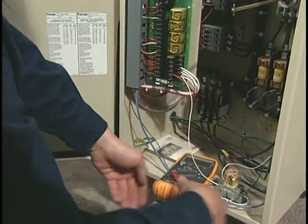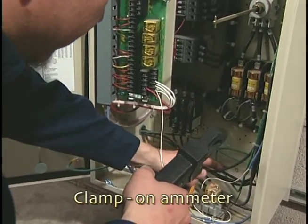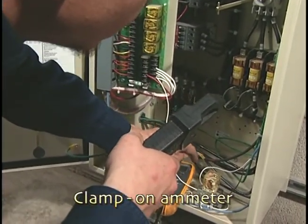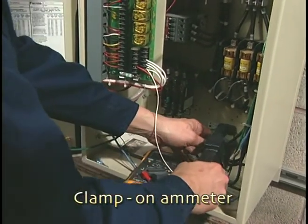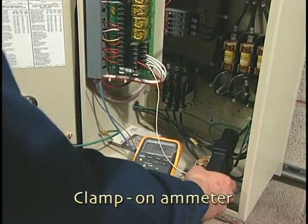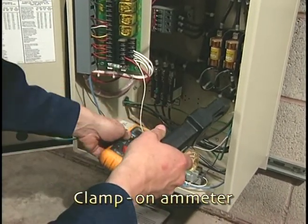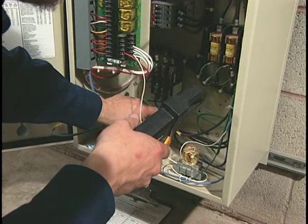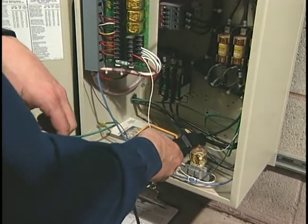Current, or amperage, is measured using a clamp-on ammeter. When reading current on a three-phase motor, all phases are measured. The technician opens the jaws of the meter and places them around each wire in succession. A good technique is to read from left to right. The technician will read each terminal wire, T1, T2, and T3.